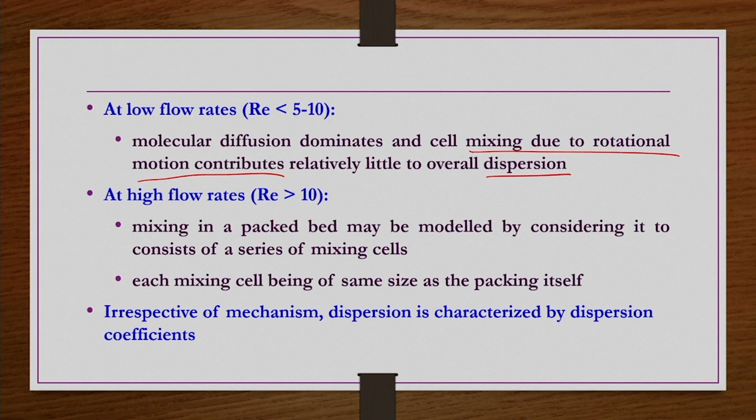In the case of diffusion, we have diffusivity or diffusion coefficient. When we are considering dispersion, we have a dispersion coefficient. Diffusivity does not depend on the flow regime and the geometry in which the flow is taking place, but dispersion strongly depends on the flow regime and also on the flow geometry.